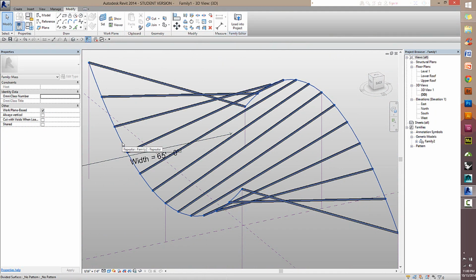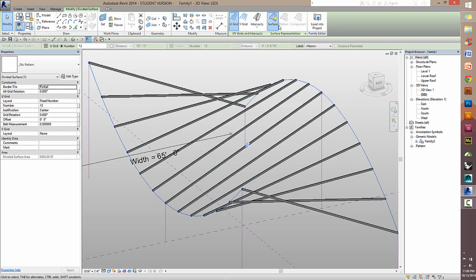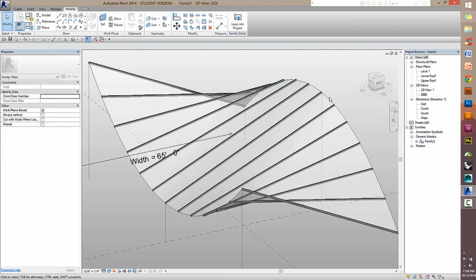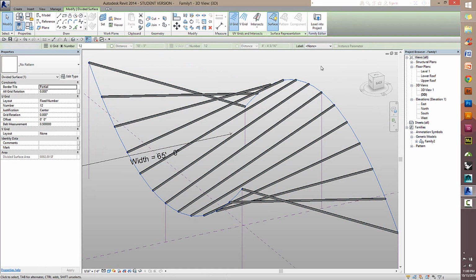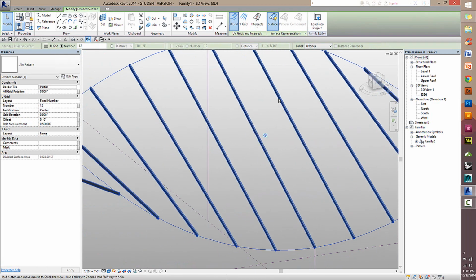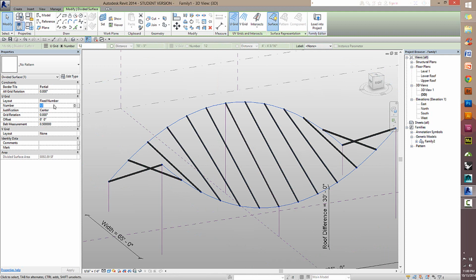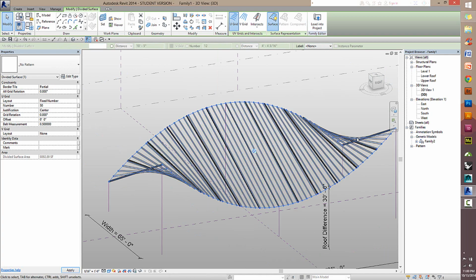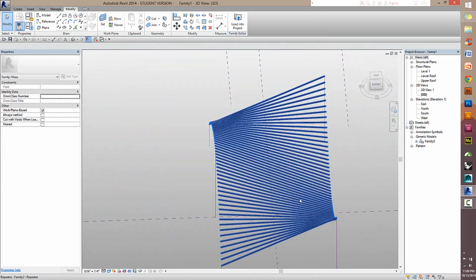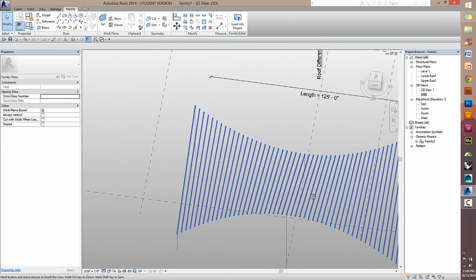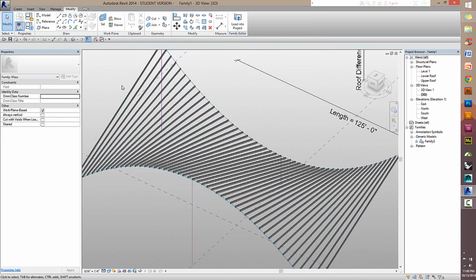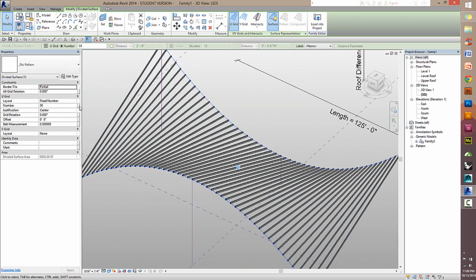To do so, select this outline here, which represents the surface that once existed. I'm pretty sure, yep, if you click this button right up here, you can make the surface visible again, but you don't actually want it visible, because it would detract from the lightweightness of these beams. Anyways, select it, and you'll see under the number in the U grid, you can change this, and it will change your parameters that the beam placement is based off of. That may be a bit too much, but rather than just changing it back, I want to do something else.